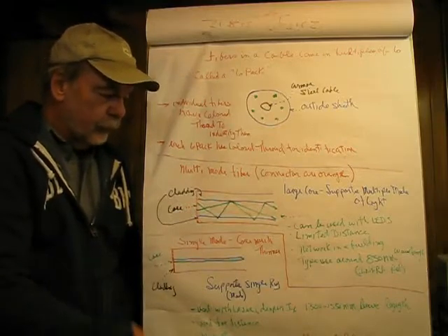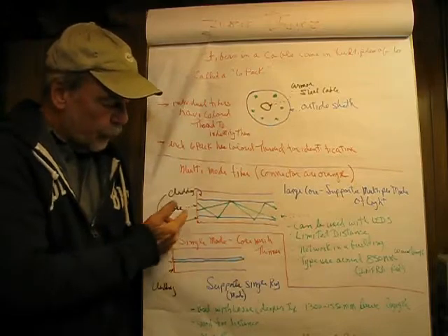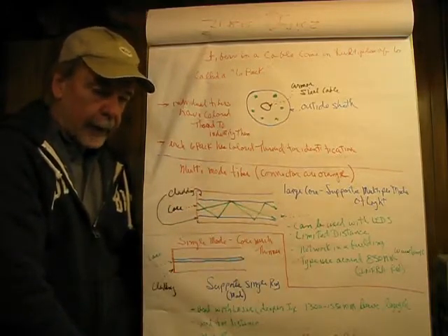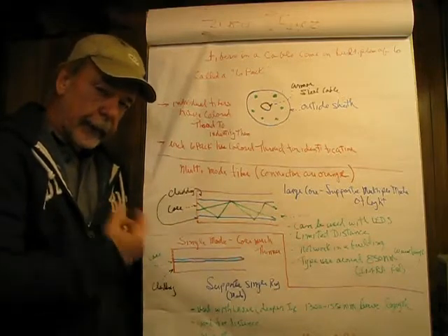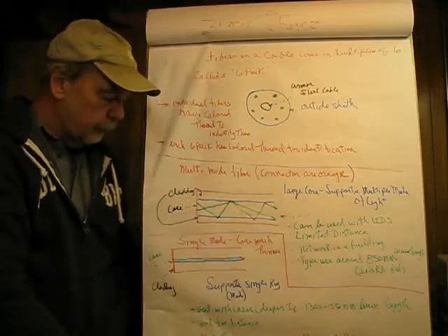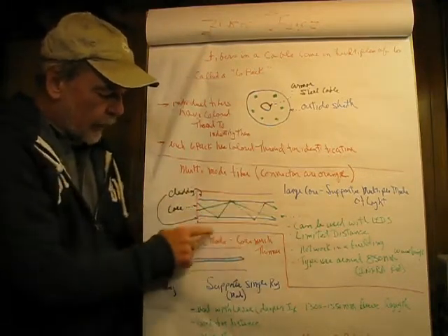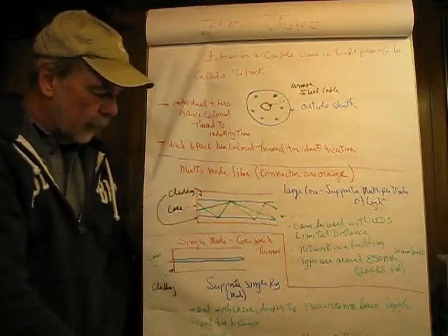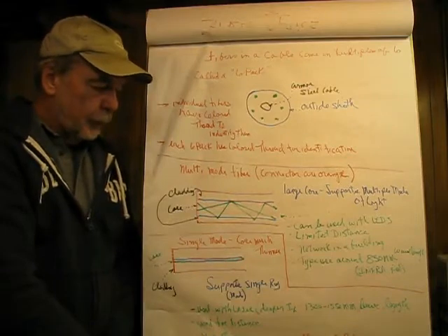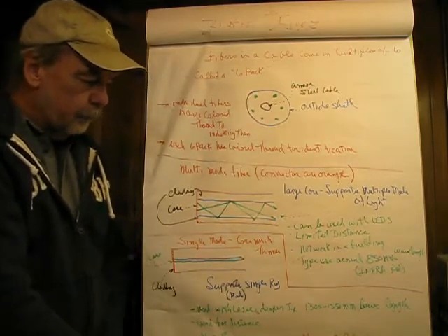So a light ray is a word typically used in fiber optics to explain what we're seeing inside of it. They are particles and waves, but ray works well for a good visual on this. So you can have multiple rays here. You can see these bouncing around. All of these here are subject to total internal reflection, and our hope is they end up coming out of the other end of the cable.